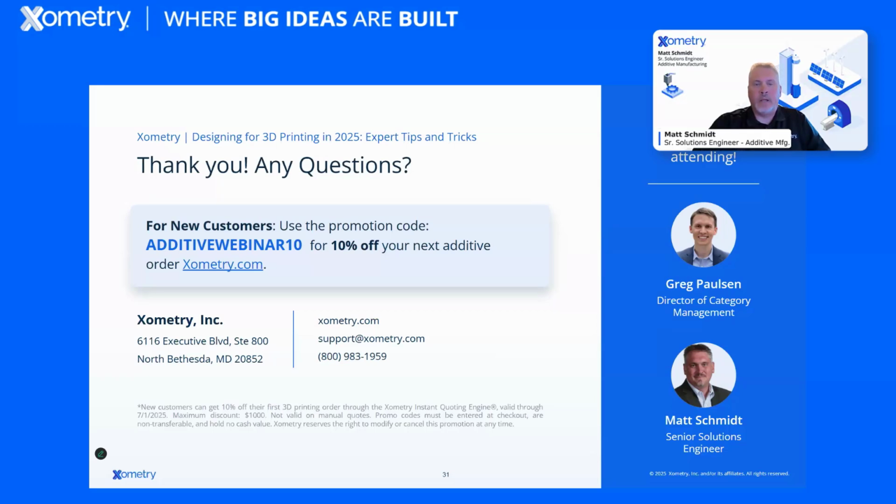Absolutely. And a quick pro tip on that, document everything you do. On a detailed drawing, document what material you used, what machine you used, what process, the part orientation, pack density. Document as much as you can to make your part repeatable and reliable in the future, so you don't have to reset and do it all over again.